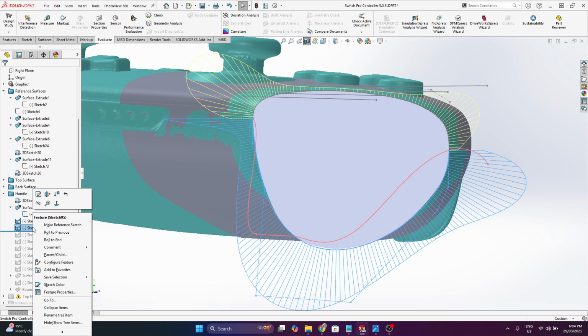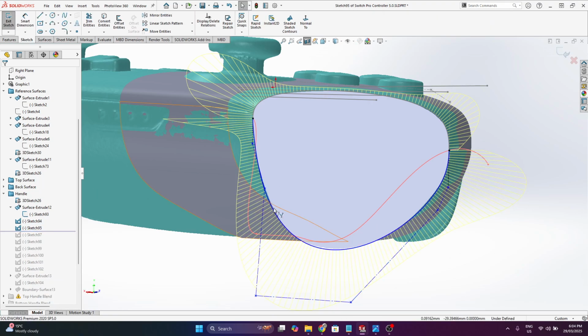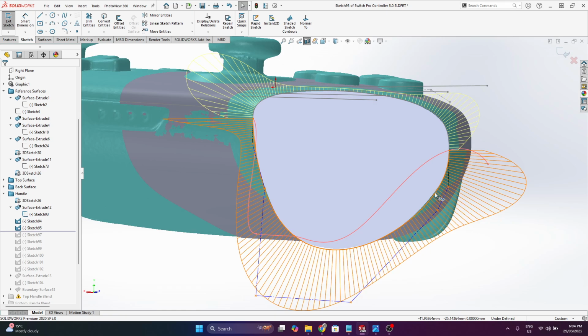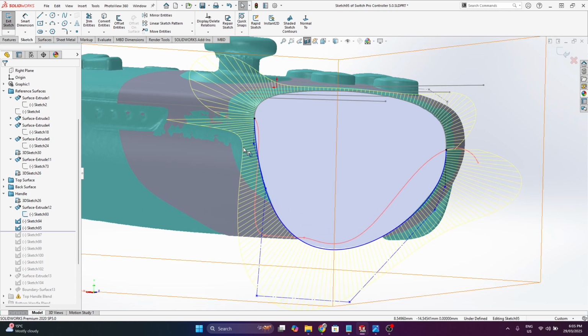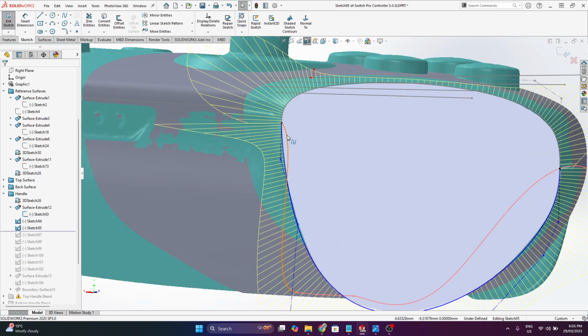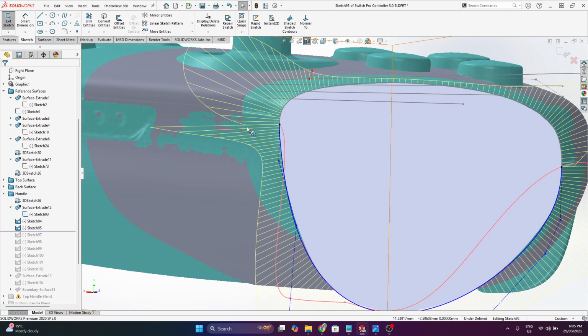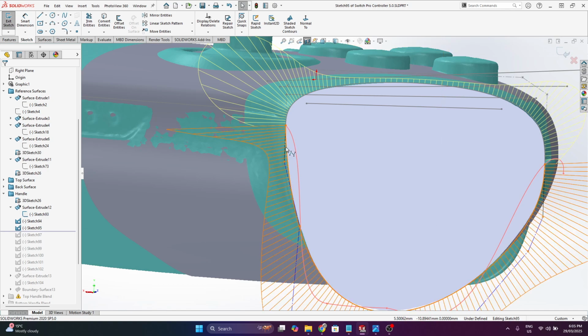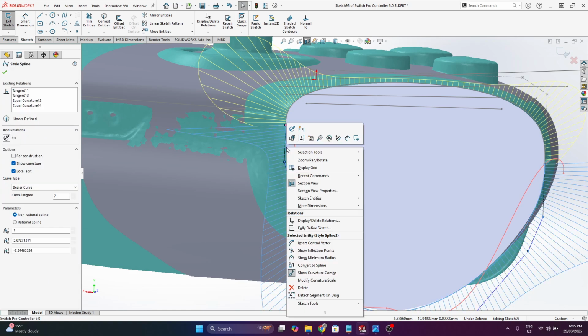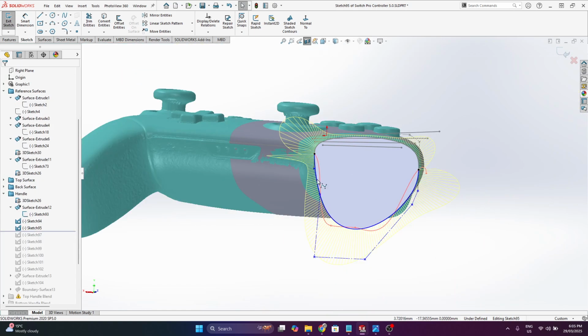And again, I just did a similar one on the bottom here to line it all up. One thing I found that SolidWorks does, I'm not exactly sure why, is that if you look at these curvature combs, for curvature continuity there shouldn't be a spike here or a gap. It should be a smooth transition. But it actually is. It's just a different scale, because these are in different sketches.